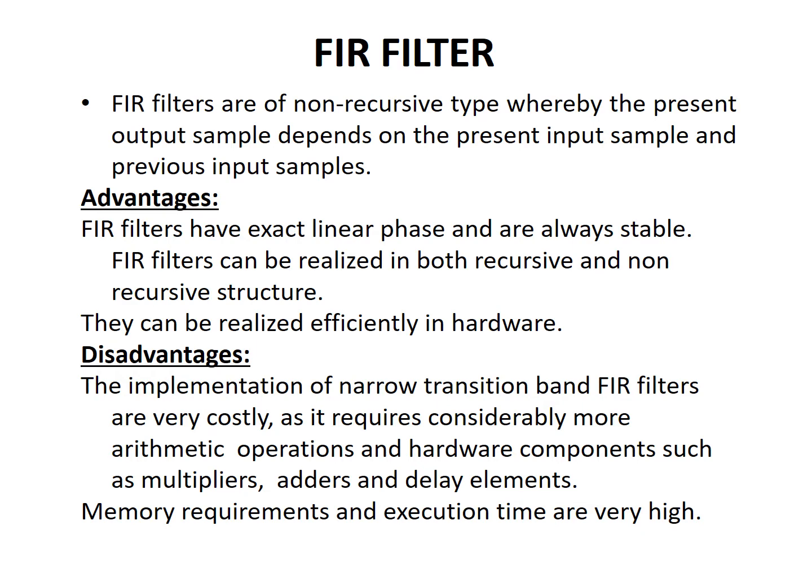So we can say that FIR is non-recursive because the output sample depends on the present input and also the previous input samples. Advantages: FIR filters have exact linear phase and are always stable. FIR filters can be realized in both recursive and non-recursive structures. They can be realized efficiently in hardware.